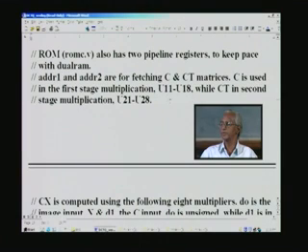C is used in the first stage multiplication, and next, having got C from the ROM and also x from the dual RAM, what we need to do is the multiplication. Remember that we had 8 multipliers in the architecture, and we will be invoking 8 such multipliers, each of them instantiated as U11 through U18. Similarly we need to evaluate the outcome results, which will have to be added, and the added result will again be multiplied by another set of 8 multipliers in order to have the last DCT produced using the CT matrix.